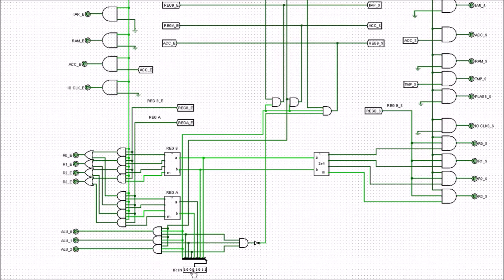Then there's 0, 0, 0, which could be anything, so we've got 8 possible combinations of these 3, and these go into the AND gate as well. But there is one other point that also controls whether we actually give the opcode out or not, and you'll see that it's further up here, so we'll see that in a minute. Ostensibly these 3 bits will come out and choose the opcode. So these head out of the control section, and they go straight into the ALU.